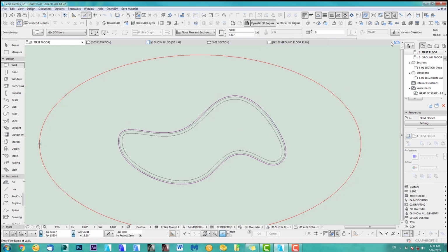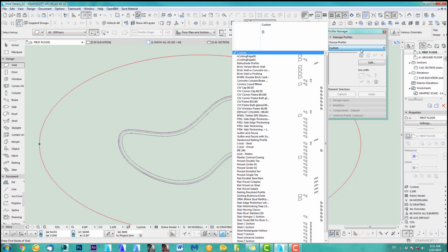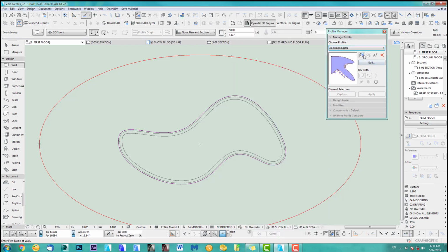Again, I use the profiler, and what you do this time is you take this one. I use this ceiling edge and I duplicate it, or if you want to, you could add the handrail on to your ceiling edge. I usually do it separate because I just have more control over it. So I duplicate and we call this a void handrail, and let's make this 0, 0.